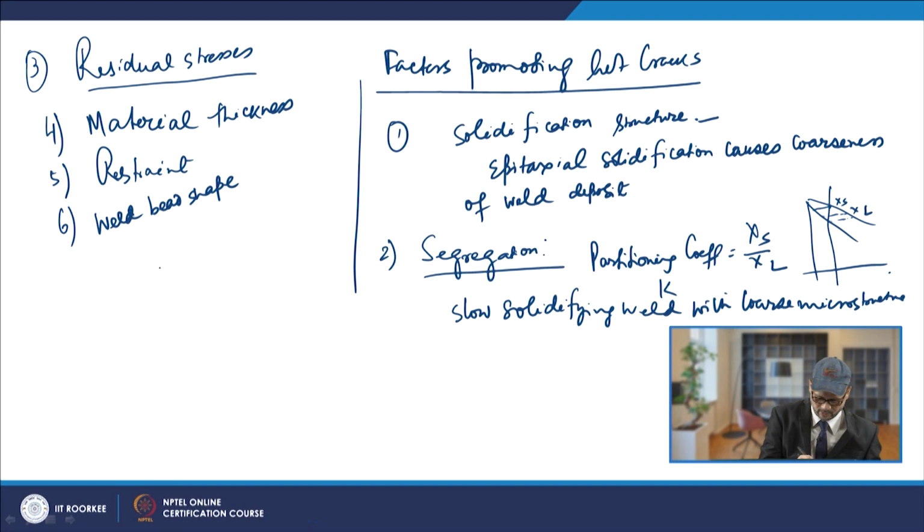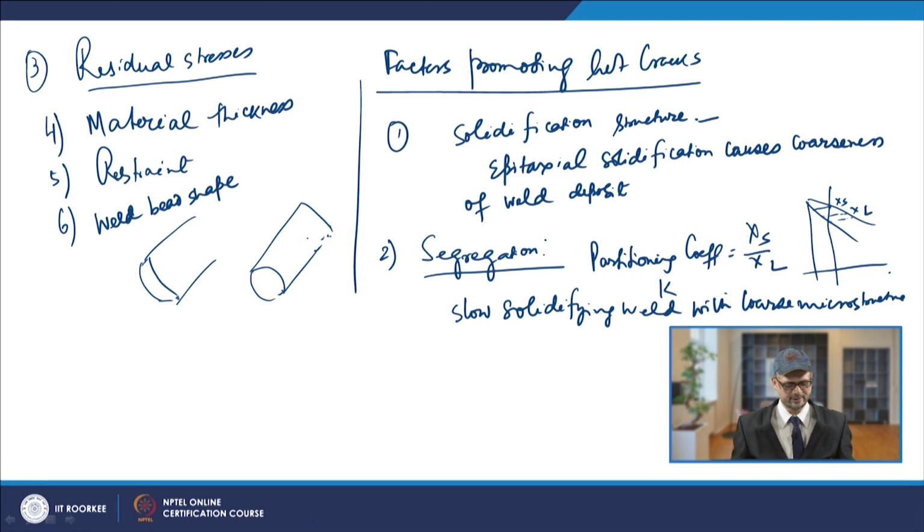So you may have such a shape, or this kind of shape. The concave shaped fillet will be larger than the convex weld, but the concave fillet will have lesser penetration into the welded plates, and so a smaller throat than the convex type of bead.